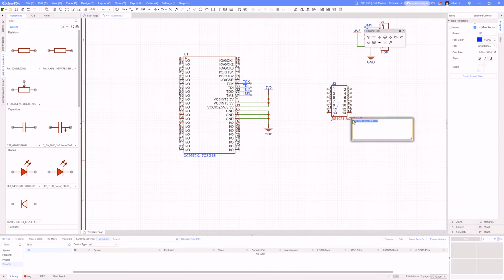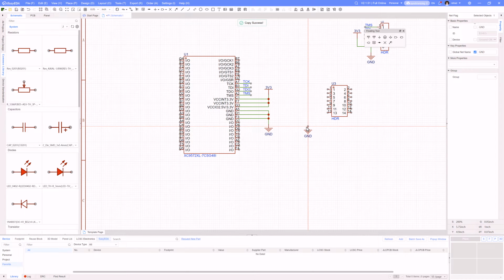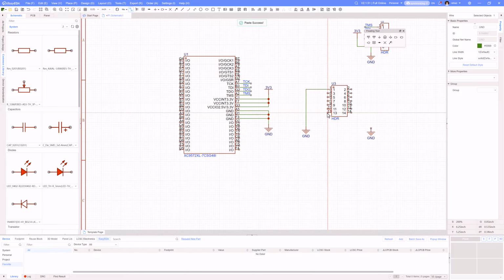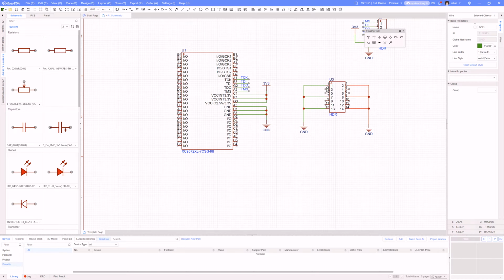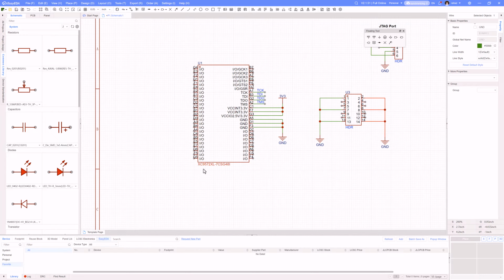And I'm going to simply relabel this as header. And I think I'll use a format that looks like this. I'll put a couple of grounds out here. And then I'll connect up the ends to ground in the middle. And that gives me this kind of format I've been using on some of my previous projects, if you've watched any of those videos. But now I have 8 pins left, and I can hook up some signals to that. I've got all these I/O pins.